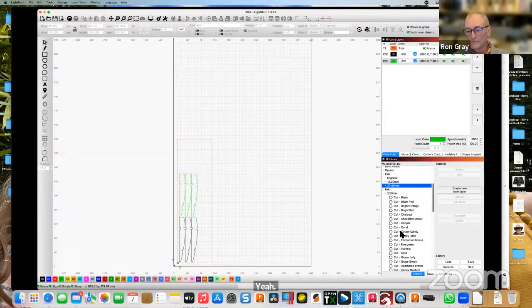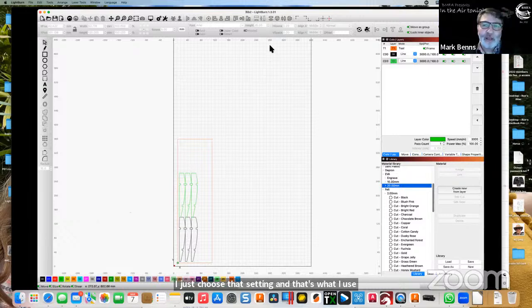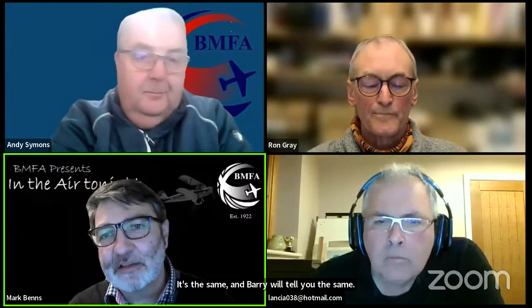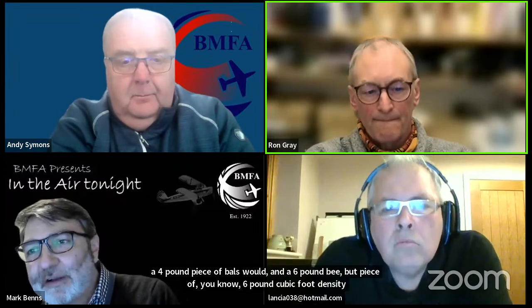Next time I've got to cut some of her copper colored, I just choose that setting, and that's what I use. No, that's absolutely it, Ron. And I can advocate it's the same, and Barry will tell you the same. We all test and test and test. Yeah, I can tell you when I'm cutting indoor balsa down to 15 or 20 thou thickness, the different density of balsa requires a different setting, and some people just do not believe that. But I can tell you, the difference between a 4 pound piece of balsa wood and a 6 pound per cubic foot density is a phenomenal difference in the laser cutting.